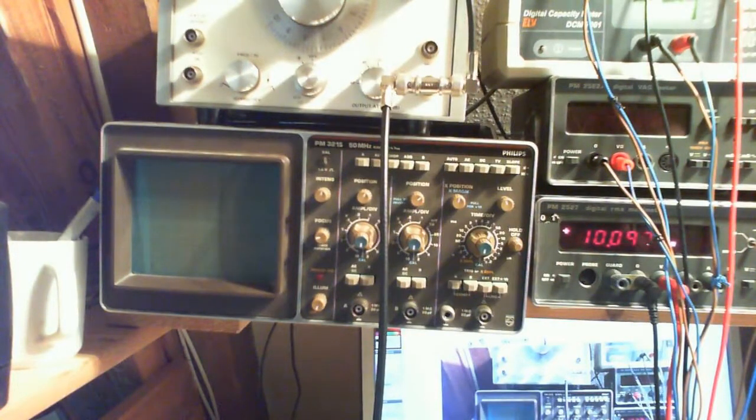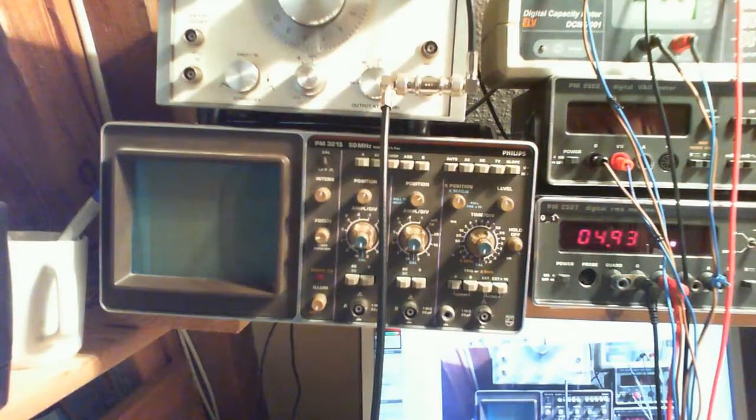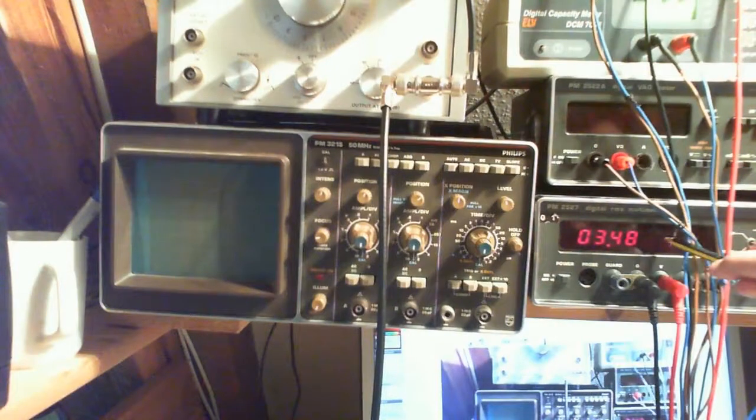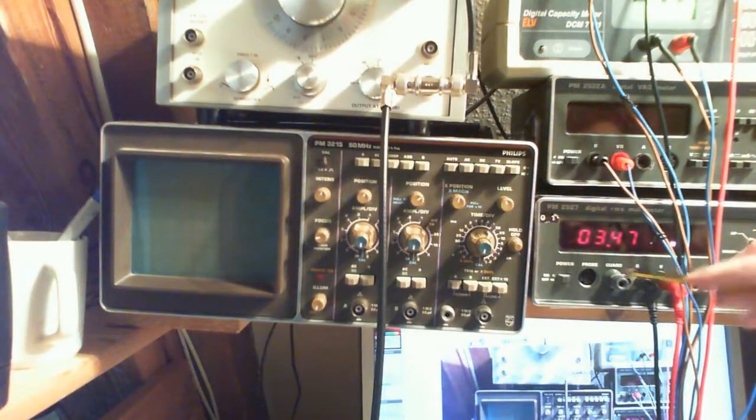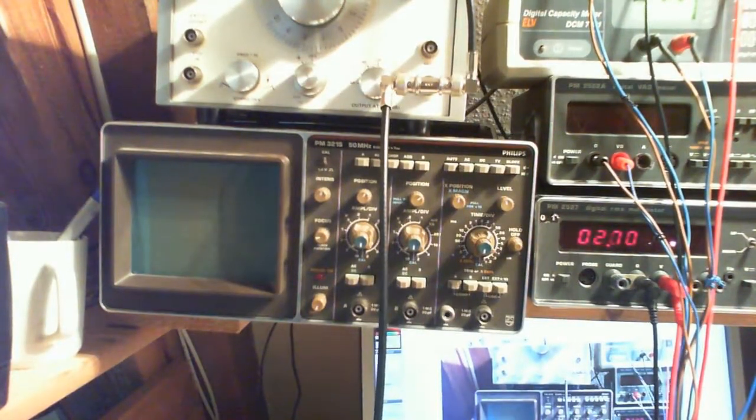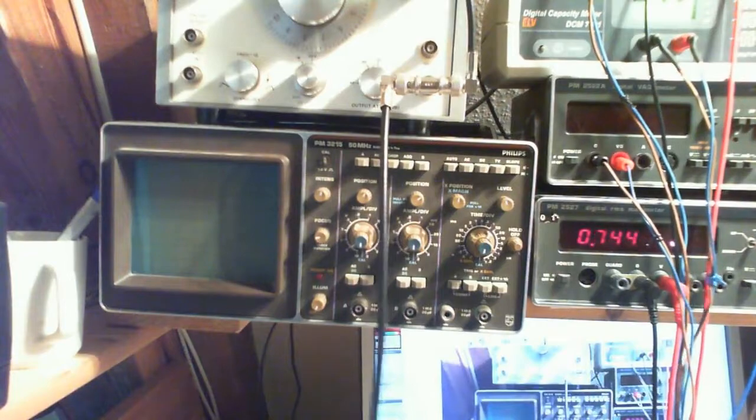So that's basically my signal. And while we are here, I can also show you the signal itself, and the signal itself was 10 volts peak to peak, as you remember. So if I go to AC, basically you can see that you can read 3.48 volts. And this is an RMS voltage. So 3.5 volts, let's take that as 3.5 volts.